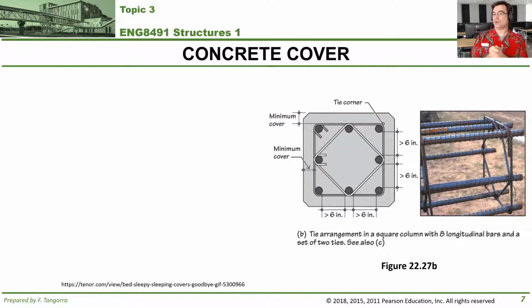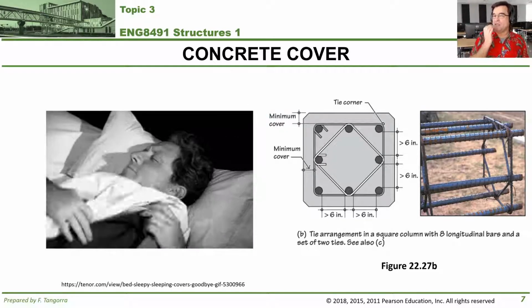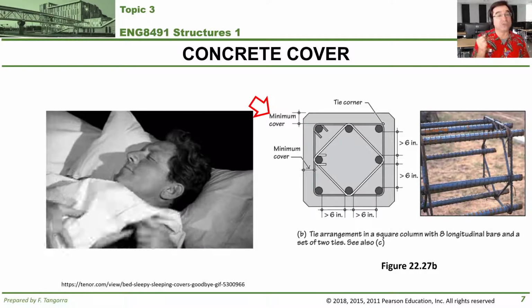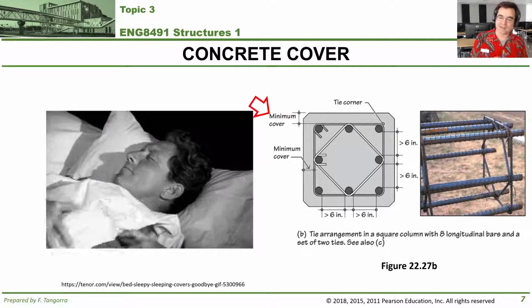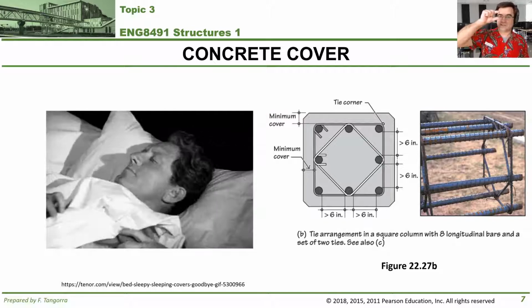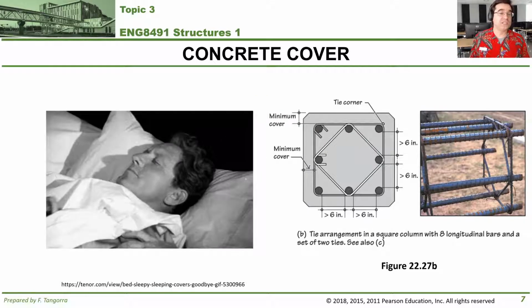So depending on where you are in the world and the kind of weather conditions you have to weather, or the use of your reinforced concrete structure, you have to add a thicker or thinner layer of concrete on the outermost steel to cover it and minimize the possibility that water or any other agents can affect the rebar and cause it to deteriorate, to rust, and therefore negatively affect your structure. So that's what concrete cover is: that minimum thickness of layer that covers the outermost steel reinforcing.